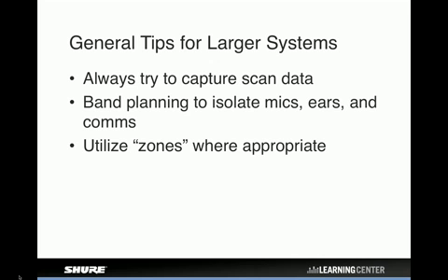And then lastly, there's the concept of RF zones. You could use the MGM Grand as an example. There are often multiple venues using wireless within that theater. If you can do an overall coordination for the casino where you take each room or each venue within the overall structure as a separate zone, then that will often allow you to get more channels on the air. So zoning is another good way to increase that channel count.